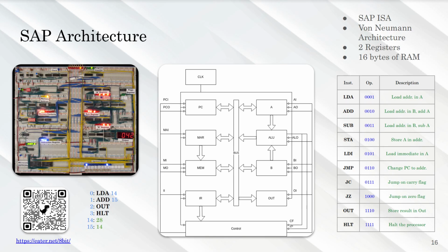Then we have the memory where the content is stored, and we have this memory address register which says, okay, we have to feed this address into the bus. And finally we have the instruction register, which holds the instruction we are currently executing. So it seems a bit abstract, but we're going to dive in right after this small example.